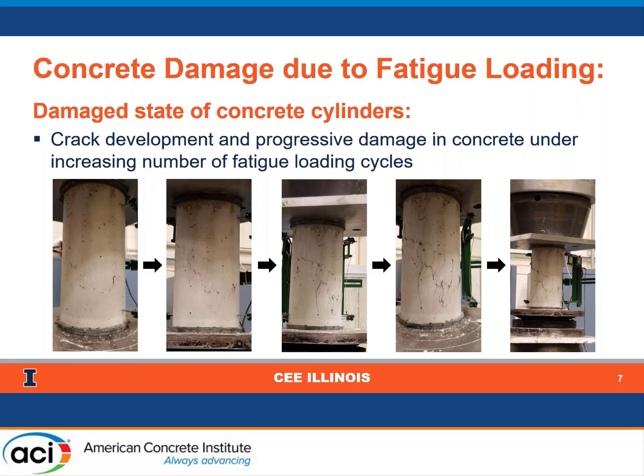In a typical concrete bridge, we might expect to see about 20 million cycles of fatigue loading. In a concrete wind turbine tower, which has a design life of about 20 years, the anticipated number of fatigue loading cycles is 500 million. So there is no data that checks the capacity up to that level. So we had to investigate, and we had to know better what was the capacity of concrete when the number of cycles could be as high as 500 million, which is why we started this investigation.